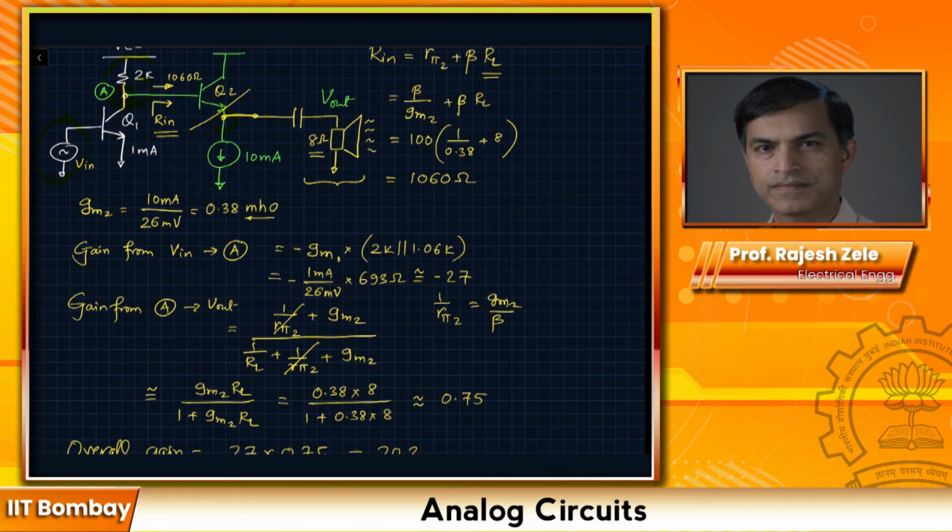For example, you achieve all the gain that you desire using a cascade of amplifiers, and then at the last point where we need to drive a low resistance, that's when you use a stage like an emitter follower, or we call it a driver stage, to finally drive the low resistance.